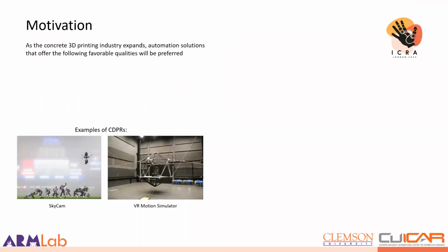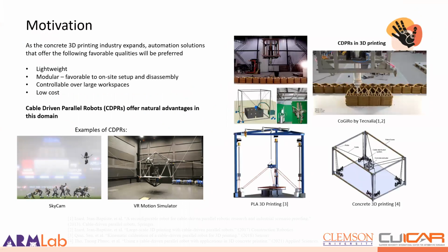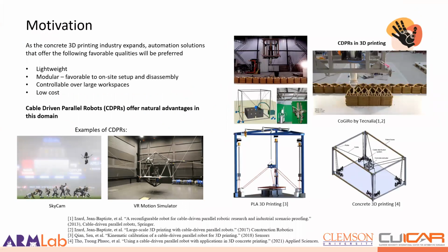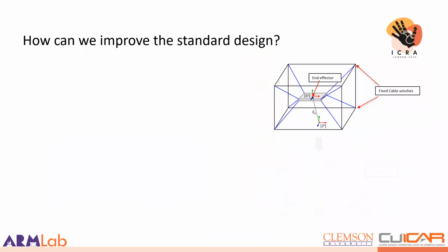The motivation for this research was to aid in the development of a cable-driven parallel robot for concrete 3D printing. Such a solution is expected to be lightweight, modular, favorable to on-site setup and disassembly, controllable over large workspaces, and of low cost. CDPRs have already been used in a handful of 3D printing applications, although there are no commercially available robots offering this technology yet.